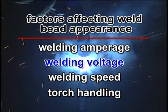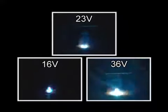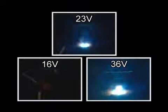Next, let's check the effect of adjusting the arc voltage setting on the weld bead. Changes in arc length are observed when adjusting the arc voltage. Differences in the arc phenomenon are observed when the voltage is adjusted between 16 volts, 23 volts, and 36 volts.